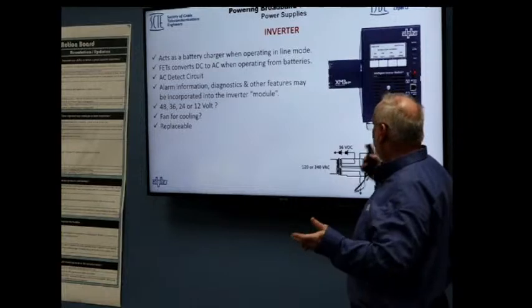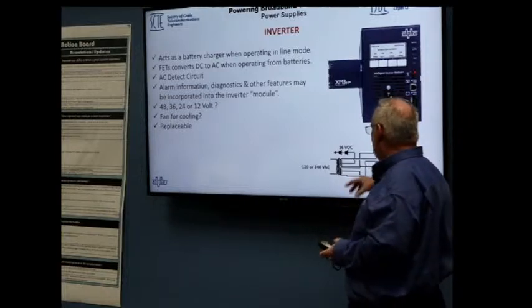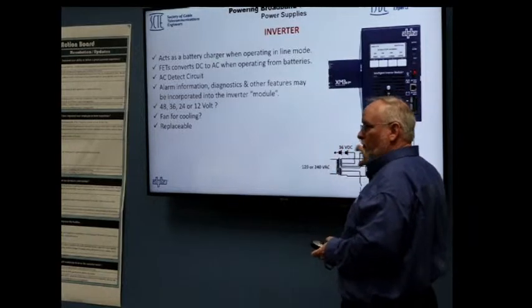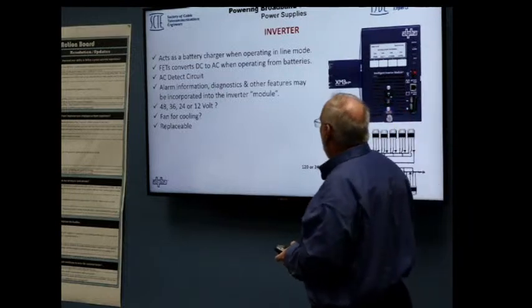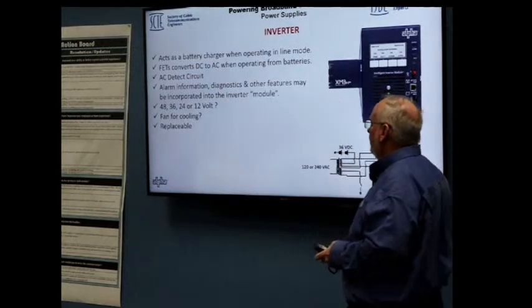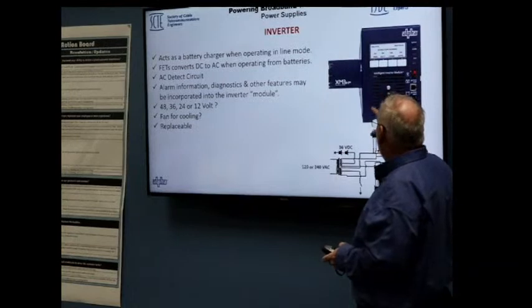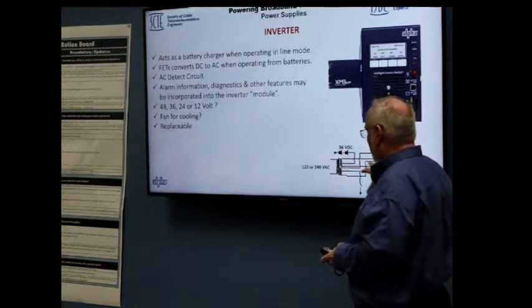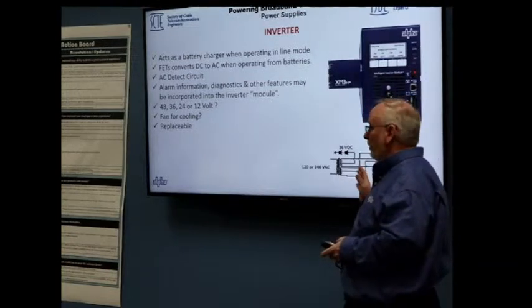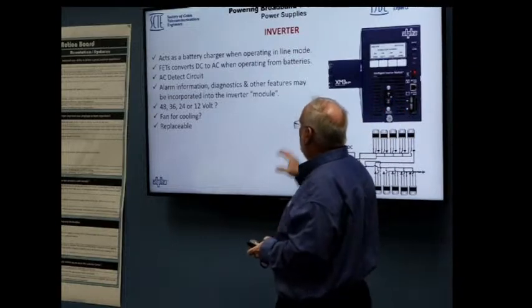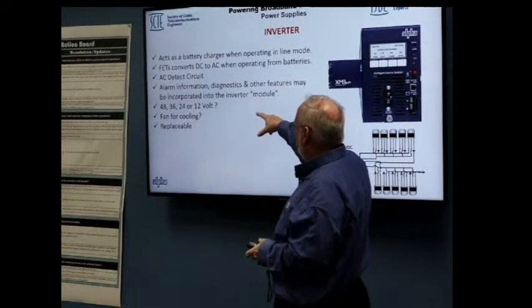The inverter section, effectively it's an H-bridge, really simple. It allows us to invert and charge using the same electronics. It does use FETs. These FETs actually do have protection in them, even thermal protection. So everything is monitored within the system. There's an AC detection circuit.